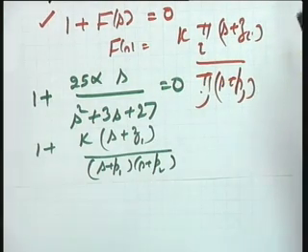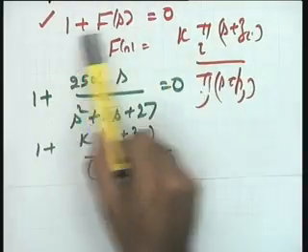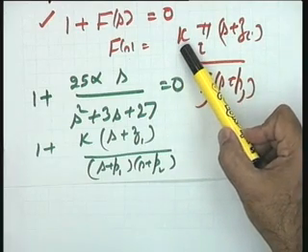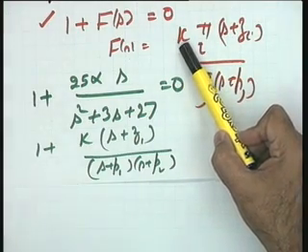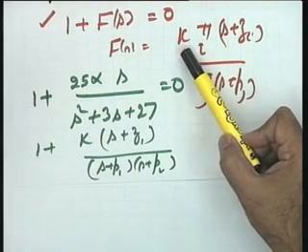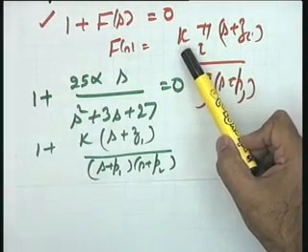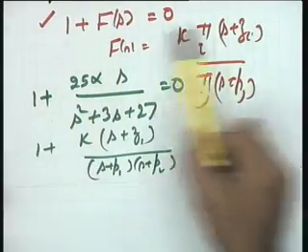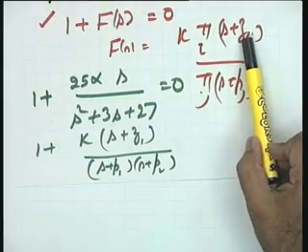So please see that the root locus plot envisages that your characteristic equation is written in this form, and in this form whatever K comes over here, I will call it a root locus gain, which is not necessary, because the word gain immediately comes to one's mind as like an amplifier gain in a system. Amplifier gain is true, but it's a very specific case of the total application of 1 plus F(s) equal to 0. It could be any parameter you want to study.